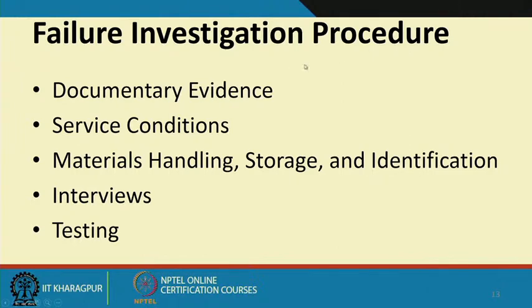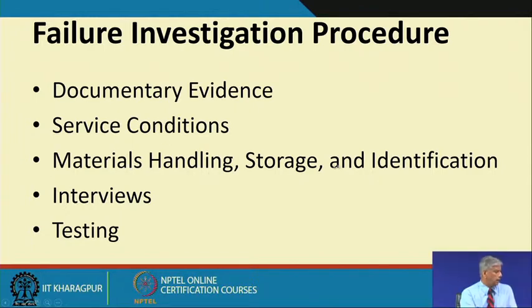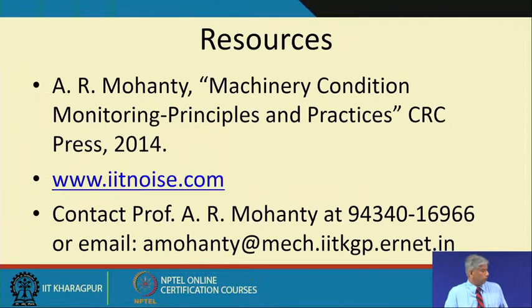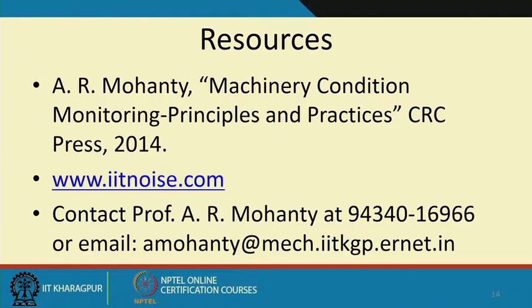So, in the failure investigation procedure, you have to document the evidence, service conditions, materials handling, storage and identification, a lot of talking to the operators and the engineers at site, and a lot of testing is to be done. Okay. Thank you.